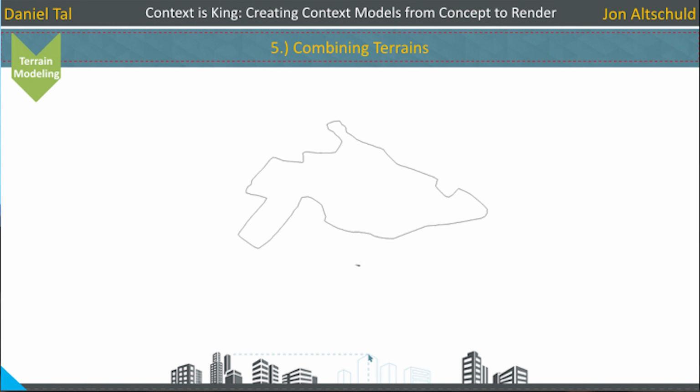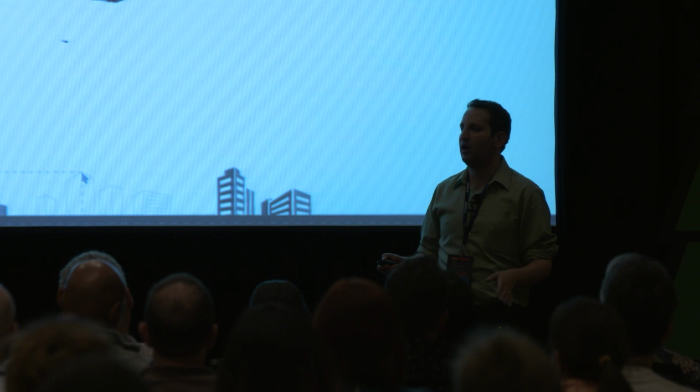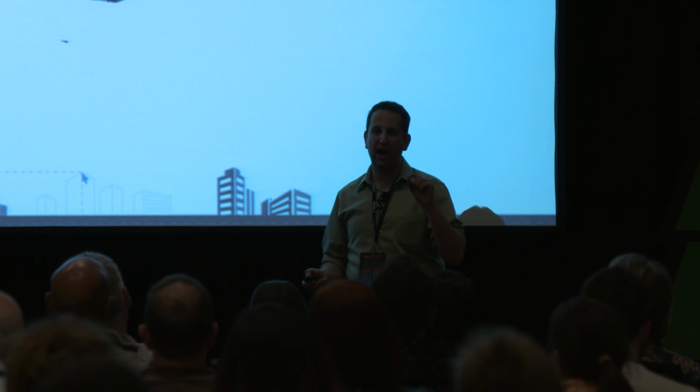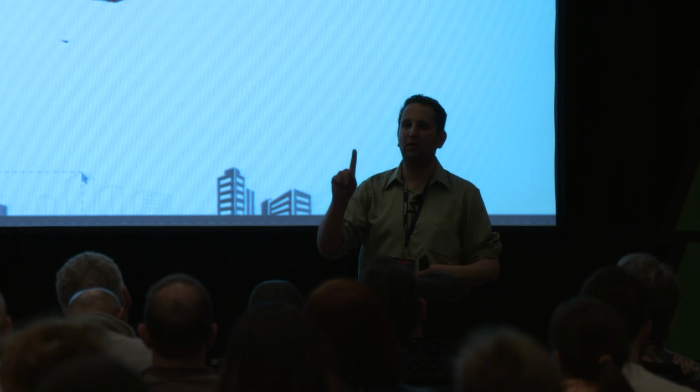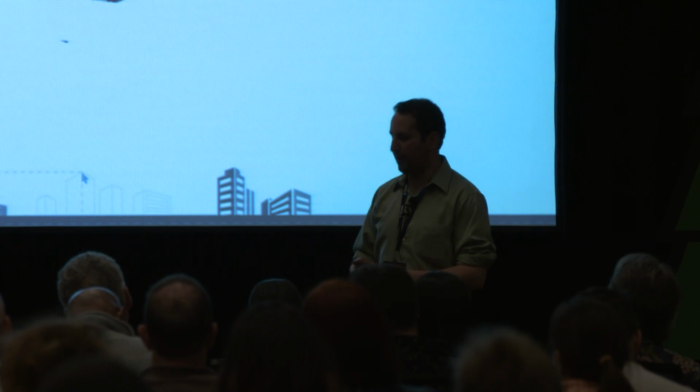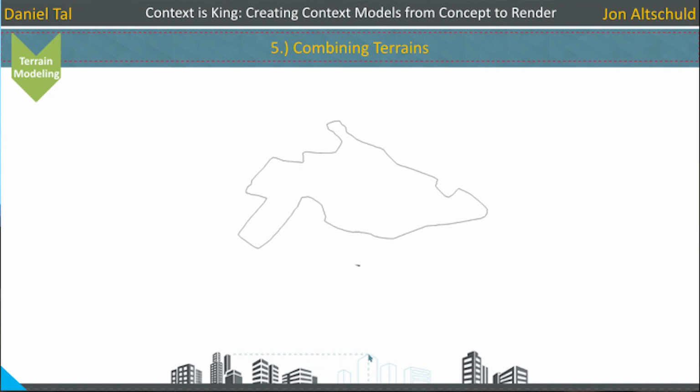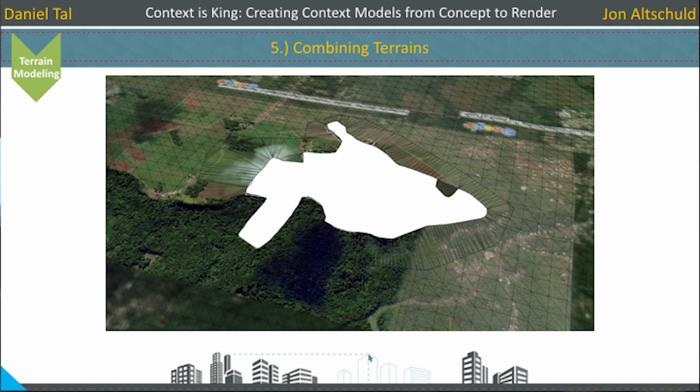We use another tool. This is an irregular outline. It's not flat, right? This is how do you stitch together all this irregular geometry. There's a great tool by Chris Fulmer. It's on the extension warehouse. It's called Select Outer Edges. Doesn't matter what you select, it will find the profile in and around the edge of a boundary. So it gives us that boundary. And then isolate that boundary line, that boundary edge. And from there, I can combine it.